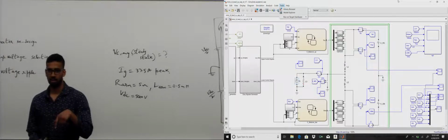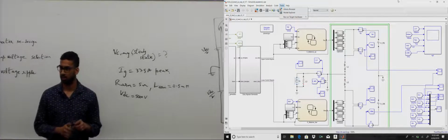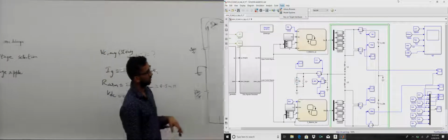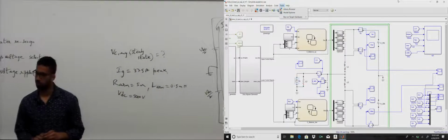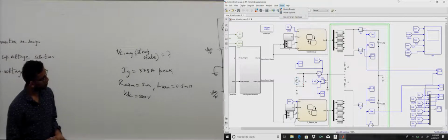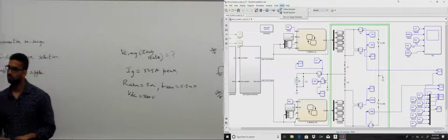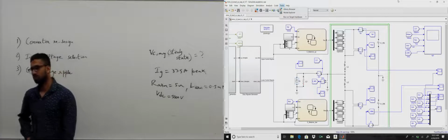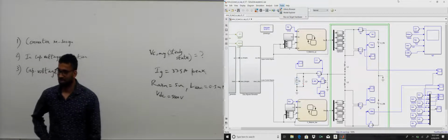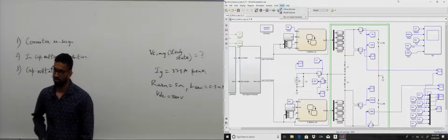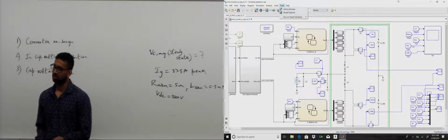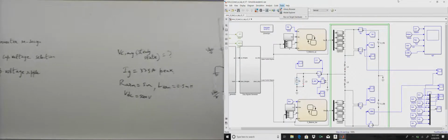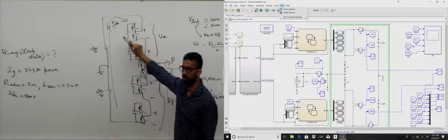We talked about that, right? The sum of the module voltages in an arm should be equal to the DC bus voltage to produce a symmetric sine wave. But the point I'm wrestling with is that if you take the capacitor voltages and multiply by the number of capacitors you have, you get twice the DC voltage. Correct, you'll get 10,000, because some of them are not there when you synthesize. You can't have that one module missing. So the average voltage at the output of each submodule is 0.5 times its DC bus voltage.